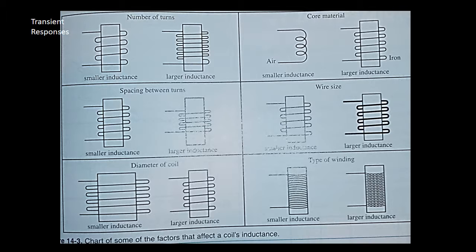Self-induction. A changing current through an inductor produces an expanding or collapsing magnetic field cutting across the wires of the coil. A counter EMF is induced that opposes the change in current. This action is called self-induction. The strength of the self-induction depends on the number of turns of wire in the coil, the length of the coil and its diameter, and the permeability of the core.